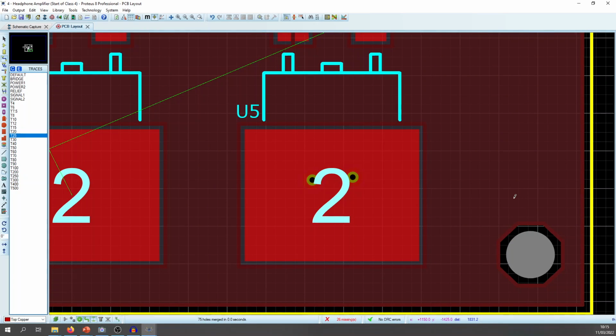Another option is to thermally relief this, where you put many of these on there. This is not the way that you do it, by the way, I'm just showing. That would be a solid thermal and electrical connection to the two internal planes.